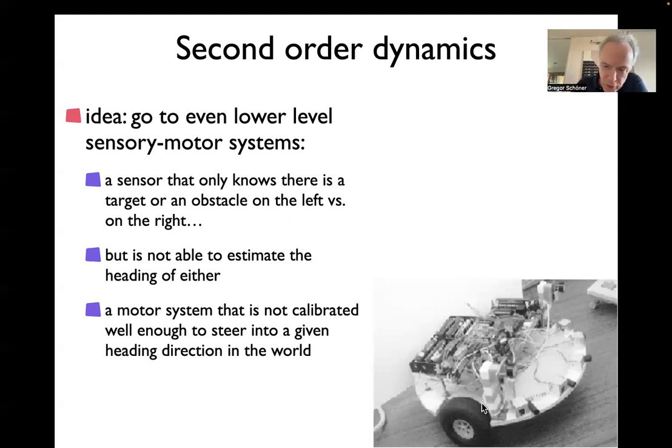And we have very simple motors. The motors were actually like toy plane motors, servo control motors. We took off the servo part by just cutting the wire, so that we just gave raw voltages to these motors, and the amount of action also depends on the resistance. So if you run this on a carpet, then it runs more slowly than if you run it on hard floor.